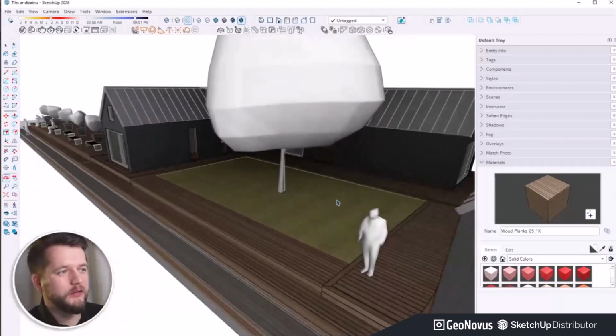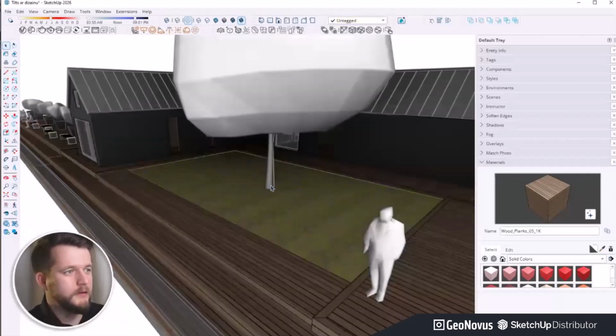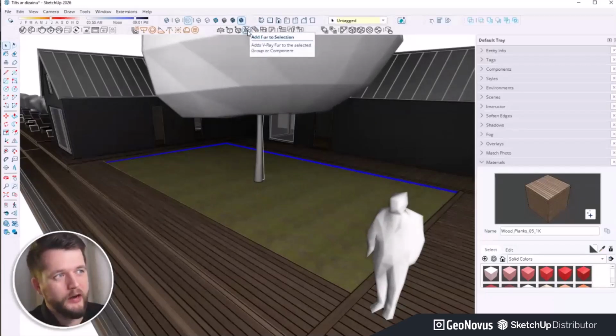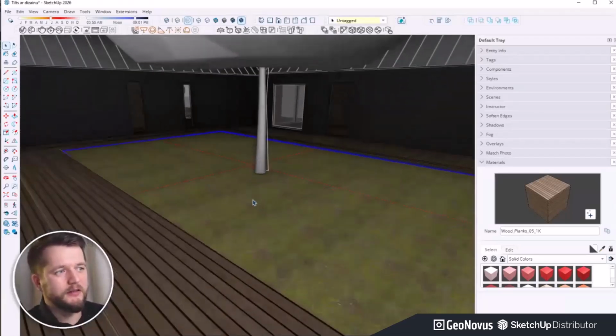And what happens with larger spaces here, for instance, I wanted to add some realistic grass. It was easy in Enscape. It's not actually that difficult in V-Ray as well, because for a while now I have this option to add fur to this object. You need to have it as a grouped face. It's maybe easier if you have even separate faces, but they're all inside the same group.